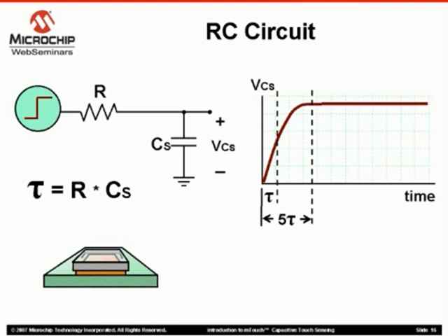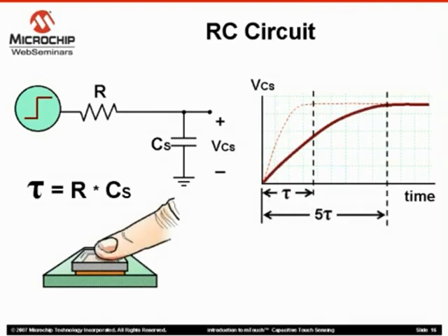The sensor capacitance alone, with no finger introduced, will create a steeper charging time as shown. If a finger is introduced, the capacitance of the system increases, thereby increasing the RC time constant, resulting in a longer charging period. Let's add a few more components to our RC circuit.